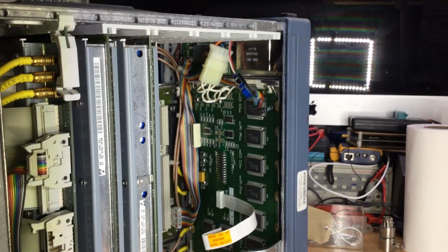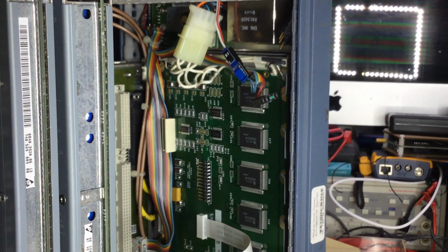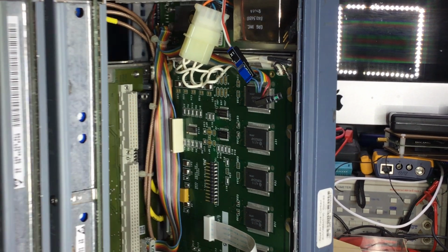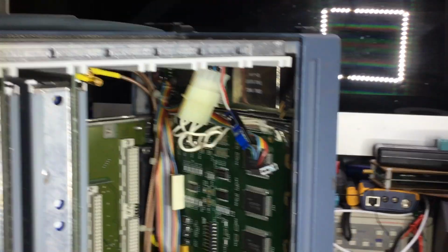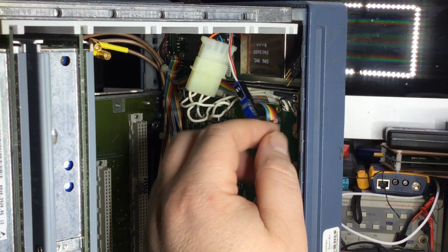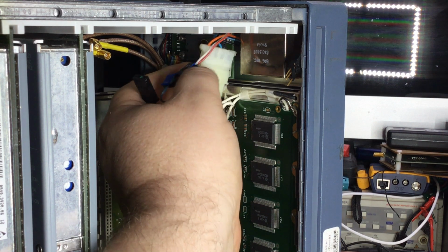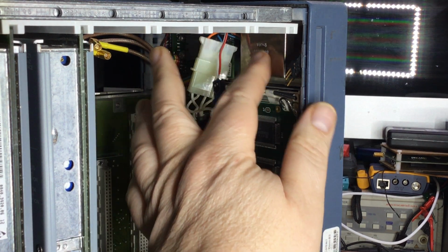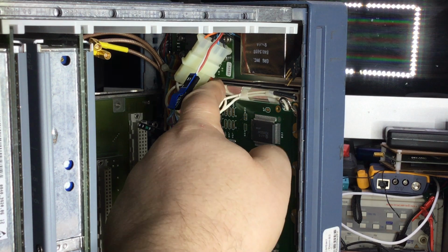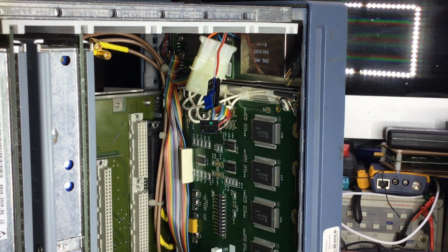But when I took the modules out, I noticed something which may answer the reason why the display backlight was flickering a little on the radio test set from time to time. And this module here is the inverter module for the backlight, the high voltage buck converter for the backlight, which is this filament here, and then there's another filament as well, I believe, which is towards the bottom of the display down here, which is hidden.